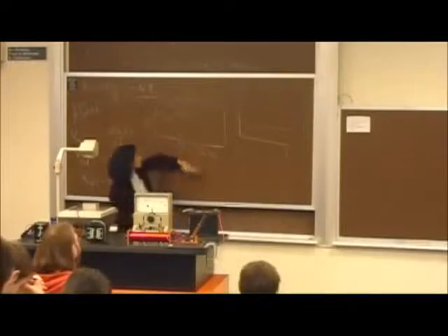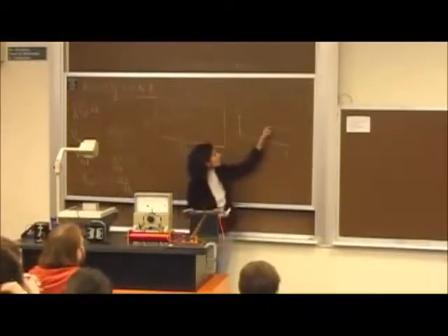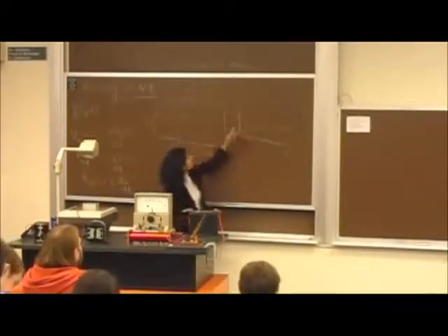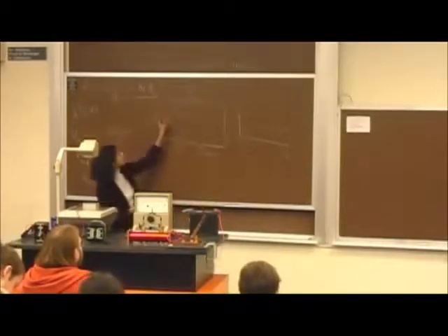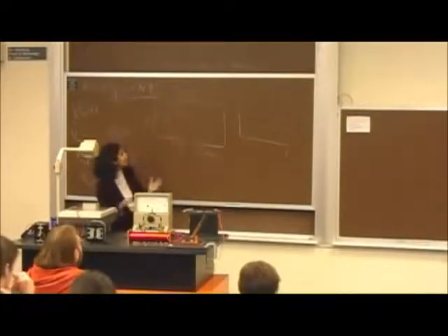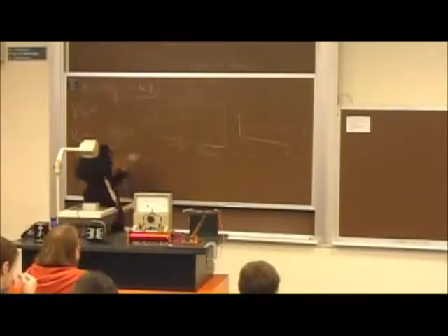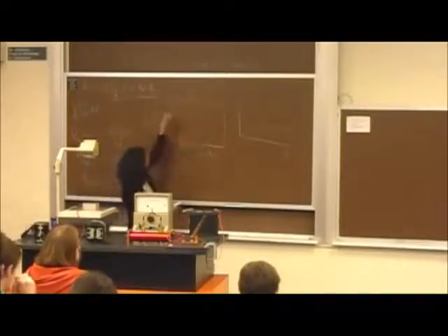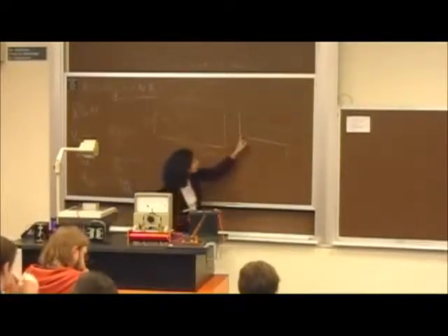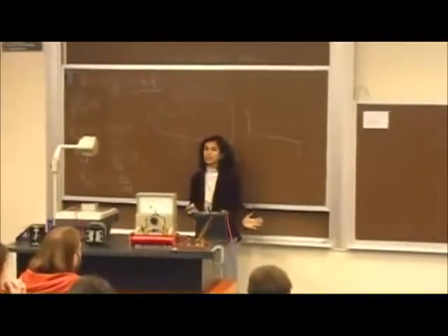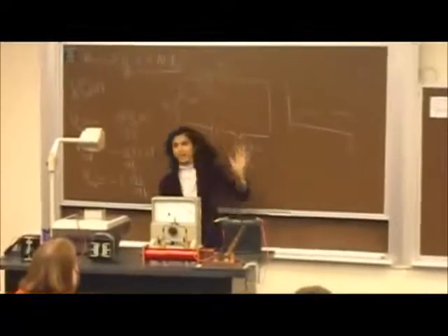Or when you open the switch, suppose the coil gets used to this thing after a long time. Suppose you close the switch, yes, initially the coil opposes, and that's why the total current in the circuit is going to be a sum of the current due to the battery and the induced current. In other words, the battery is trying to push the electrons one way, the coil, this induced EMF, is trying to push the electrons the other way. The net current slowly increases, and then it saturates out. It becomes constant, because the coil gets used to having a current through it.